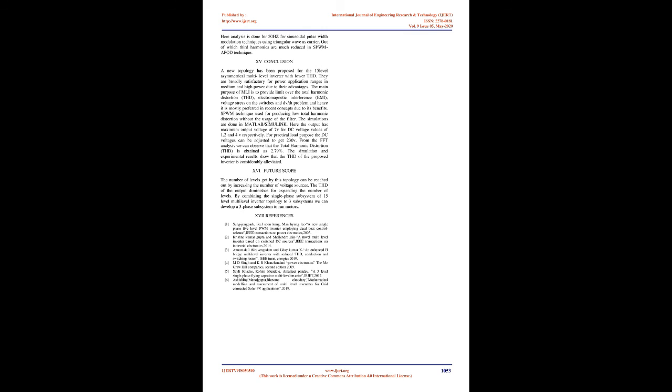16. Future scope. The number of levels obtained by this topology can be extended by increasing the number of voltage sources. The THD of the output diminishes with an increasing number of levels. By combining the single-phase subsystem of the 15-level multilevel inverter topology into 3 subsystems, we can develop a 3-phase system to run motors.